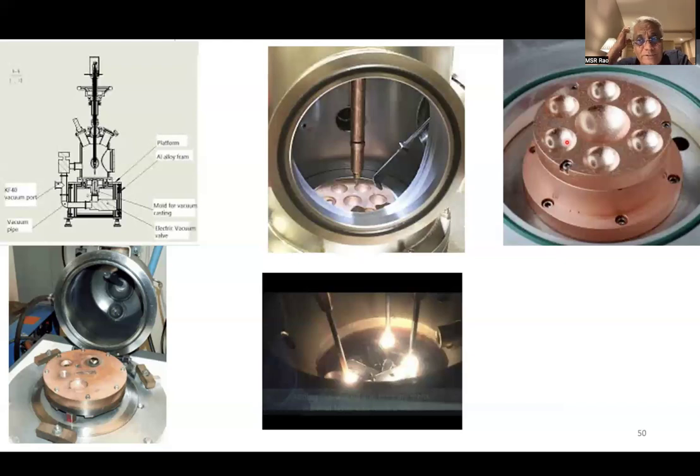The second point is, this is a mobile electrode. This whole thing is evacuated. This is a moving electrode. I bring it close to the point where the melting happens. The two ingots, two elements A and B, are there, and the whole chamber is evacuated. I have argon gas inside. The moment I bring this electrode, this is also an electrode. Your second electrode is copper, on which the whole melting process happens.